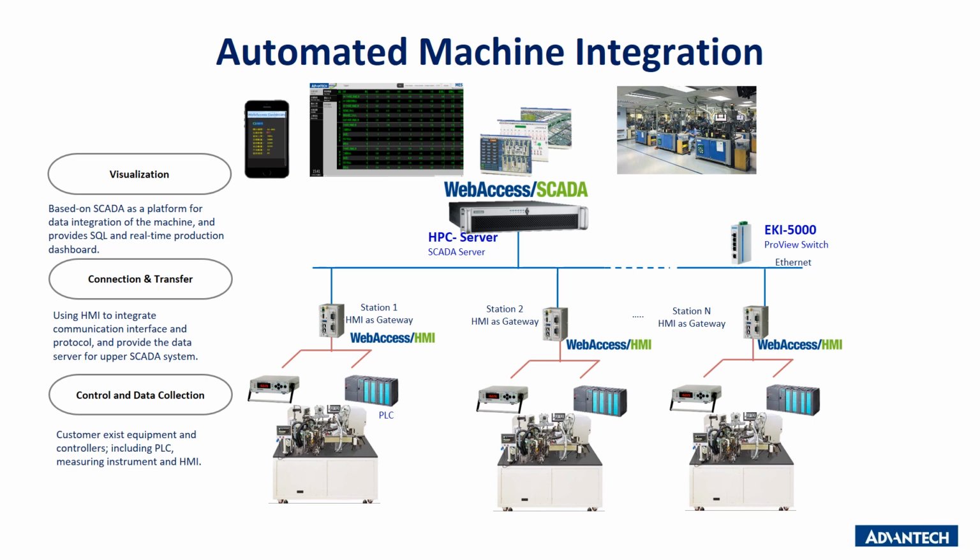In the top layer, use SCADA to collect each station's data, connect to the IT SQL database, and generate a managed dashboard for the operator and manager. Moreover, SCADA can provide a mobile access function. When we need to review current production performance, we can use the app to check real-time data immediately. It makes information automatic and reduces the production duration.